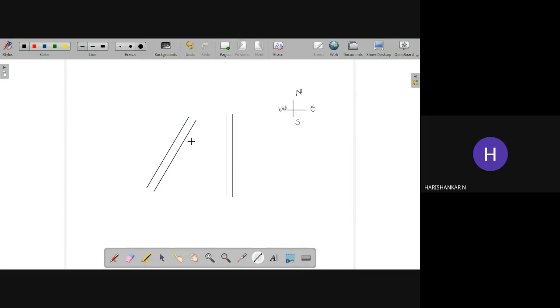So the next factor related to the runway is the, so in the runway orientation, here you can see the runway can be oriented at any direction. That means the north, south, or east, west in this way. In which direction it will be more economical considering the wind velocity.